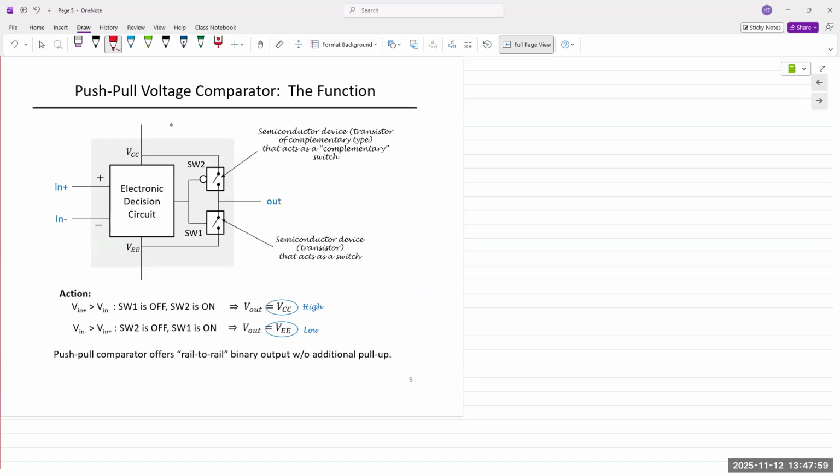But consider the fact that even if it's microwatts, 10 raised to minus 6, you have billions of these transistors in a microchip, right? Billions is 10 raised to 9. So even if one transistor has 1 microwatt of power dissipation, you multiply that by a billion, now it's 1,000 watts, right?